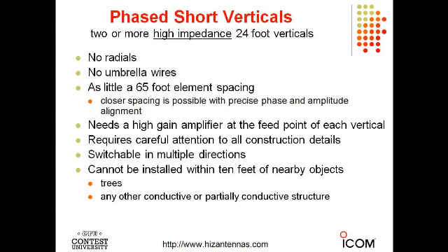You have a question? Can they be installed over an existing radial field? I don't know anyone who's tried that, but it's not apparent to me why there would be a problem, as long as the radials are not elevated. If the radials are on the surface of the ground or buried, it shouldn't be affecting the signals that are arriving at these elements. So it should be okay. But I can't guarantee it because I've never tried it. But I can't think of a reason why it would be a problem.